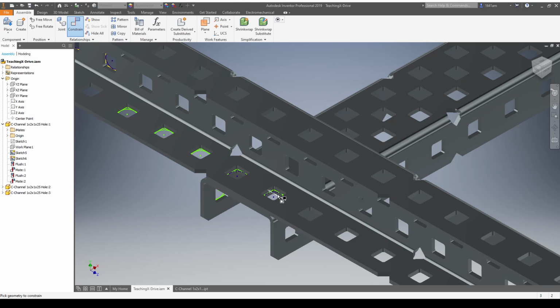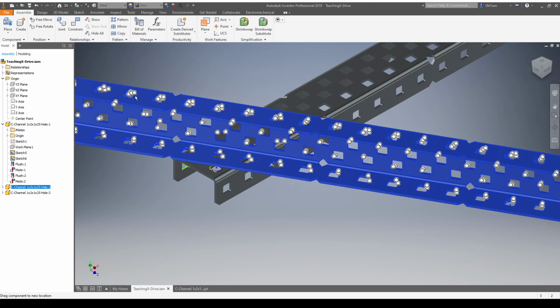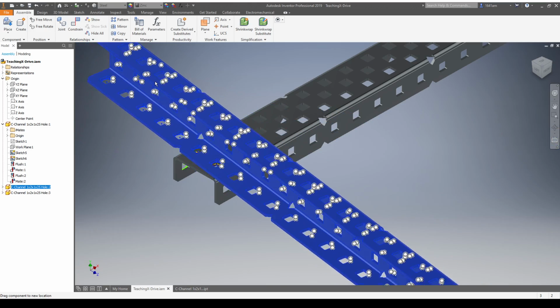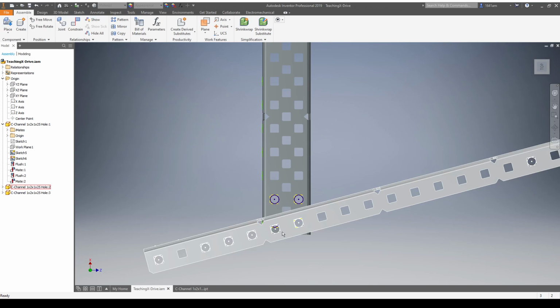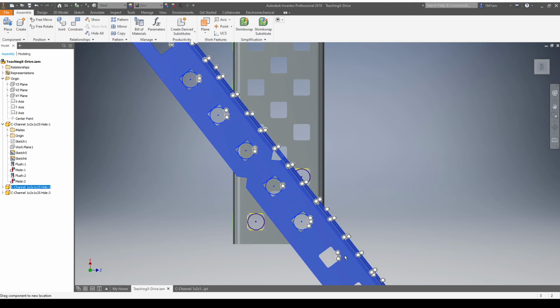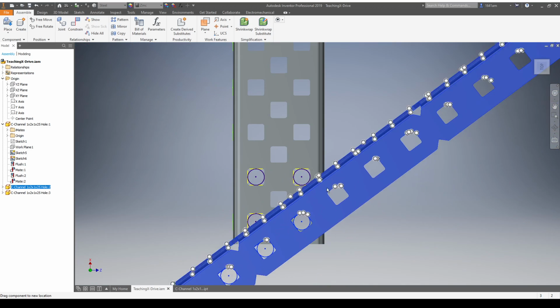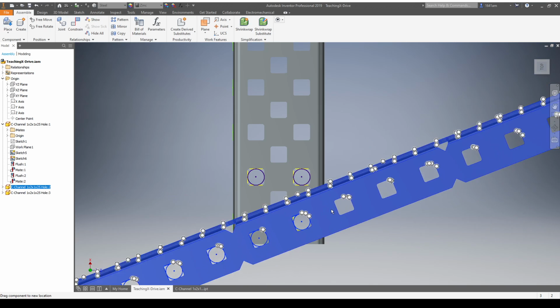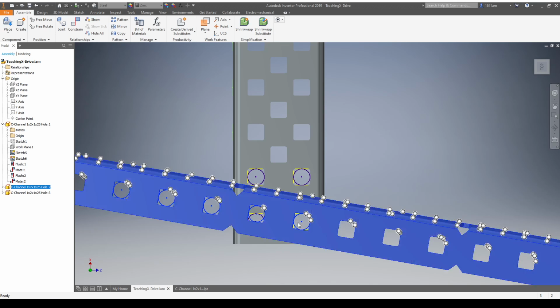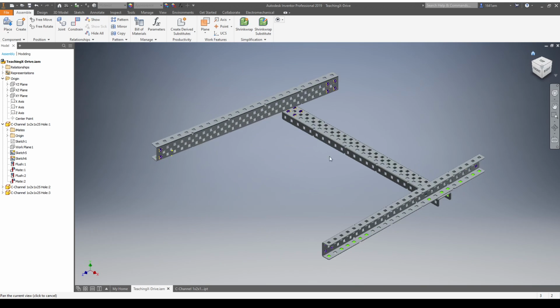And as you can see, it brings the two circles together. So those two circles are now together. So as you can see, it rotates around that axis that I just constrained. So if we look at it from the top, those two circles are constrained around each other, and the bars are stuck together. Now the problem is, it's still rotating. So next we're going to constrain these two circles next to each other so that it no longer rotates.